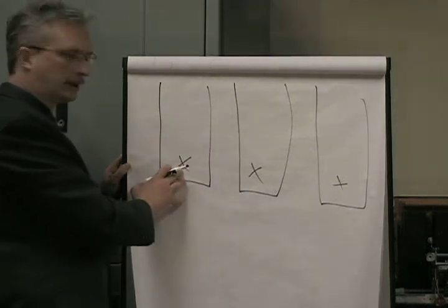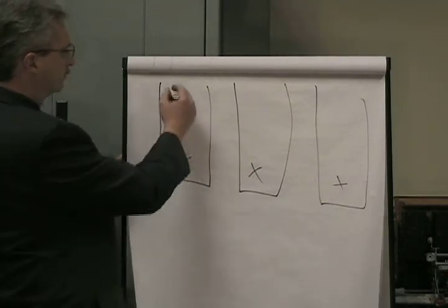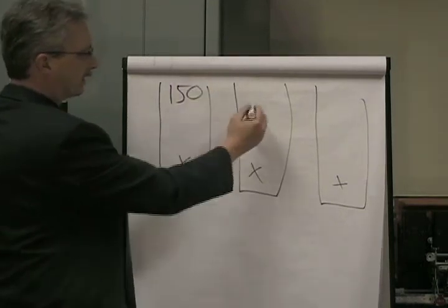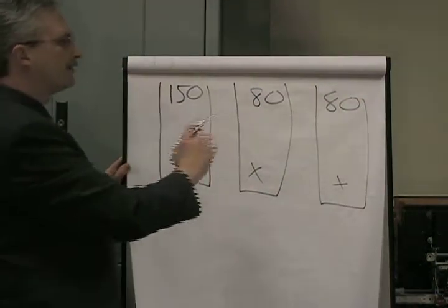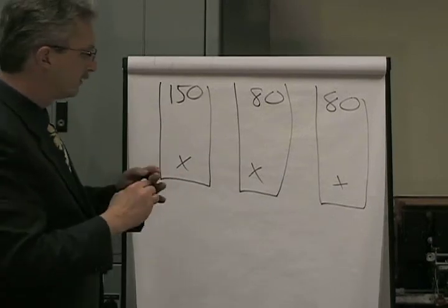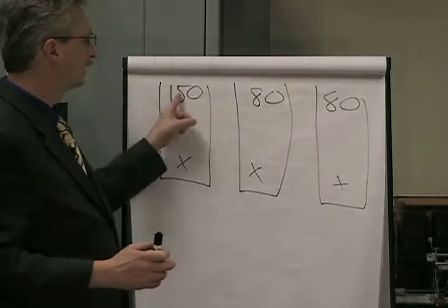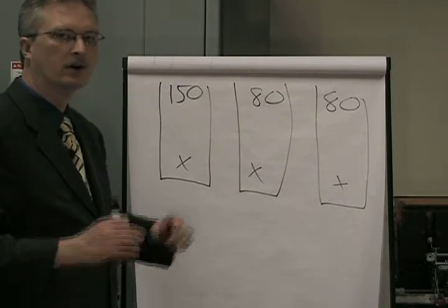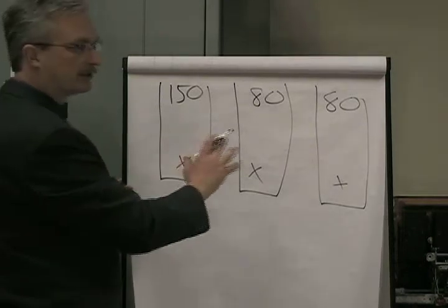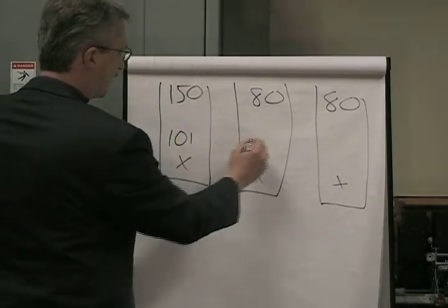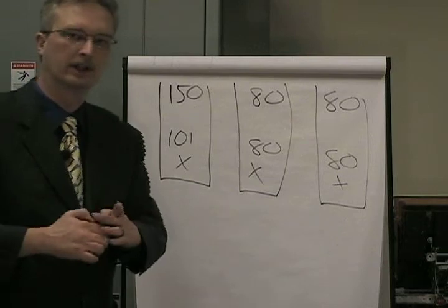The reality is that the left bus bar actually has a resistive issue and has gotten hotter. Let's say it's really 150 degrees Fahrenheit, and the middle and the right bus bars are at a normal 80 degrees Fahrenheit. That's a 70-degree rise. With the myth, the infrared camera could just look at these 3 copper bus bars and see that this one is 70 degrees hotter than the other 2 without adjusting the emissivity. That's not true. If the emissivity is not set for copper, the camera might see this one hotter than the other 2, but at a much lower temperature rise than it really is.